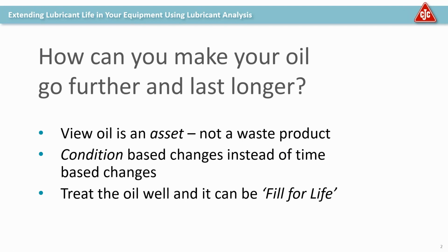Well, it really starts with our attitude. How do we view it? Do we view it as an asset, not a waste product? And that's why we're here, right? Because we're interested in this topic and why many of you signed up for this webinar. And then we realize that we need to migrate from just simply time-based changes to condition-based changes. So we recognize that oil should be changed not just based on time, but on the oil quality properties. And then finally, treat the oil well. And then we can have a scenario where it's, as many of our customers are striving for, fill for life.